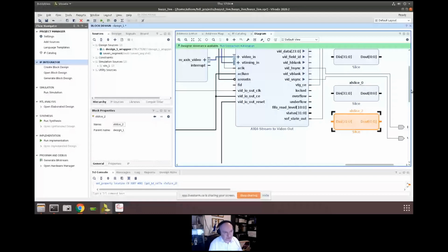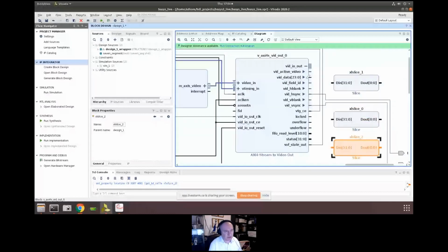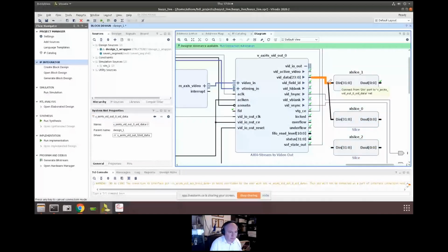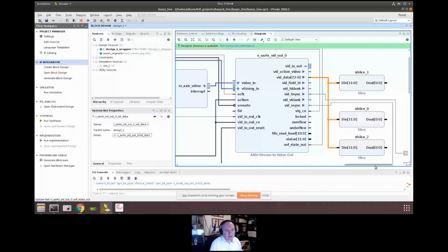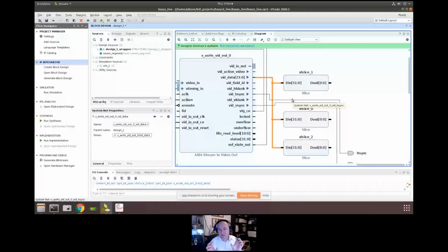So we've got a 24-bit pixel coming out, and what we need is essentially to pick off each color channel and pull it through. We need to find the correct color channel in the position, and then pull the four bits out from it. So this is what we're going to do.